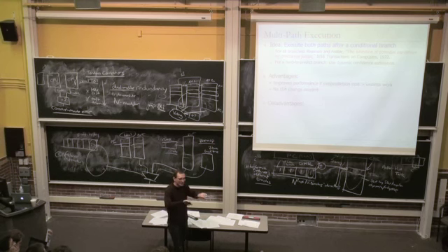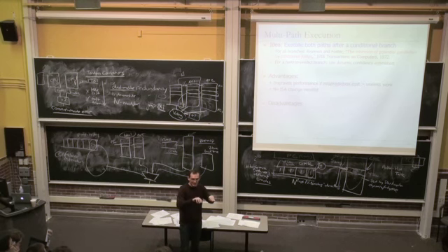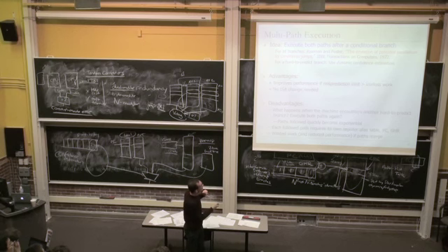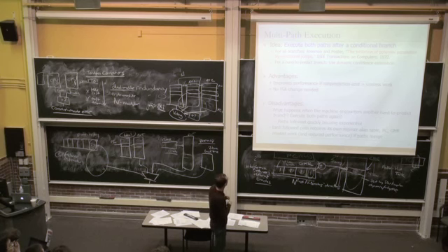Of course, you need to make sure that these paths do not write to the same registers, right? Or you should not really forward from one path to the other path. So you got to put the hardware necessary to ensure that. Otherwise, you would get incorrect execution. Which means that each followed path requires its own, essentially, context, right? It really requires its own registers, program counter, global history register, right?